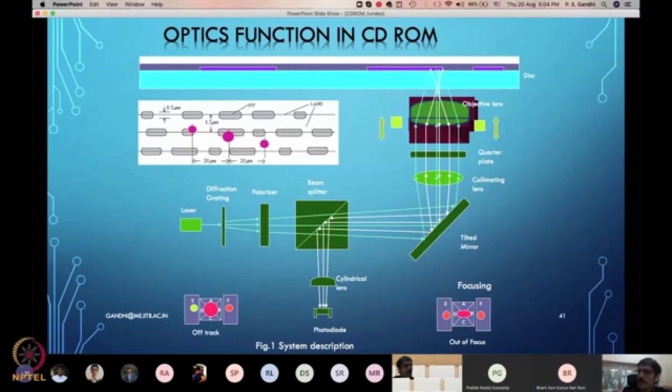Yeah. Okay, so this is about the focusing system, and now you can imagine if the side spots on the track are going out of focus, that can also be detected in exactly the same way. So instead of E and F, you will have four sensors each, A prime, B prime, C prime, D prime, and A double prime, B double prime, C double prime, and D double prime in the place of E and F. Okay, and then there also you'll correct for the focus. Then your compliant mechanism will always be maintaining the tilt also. Tilt will also be taken care of.